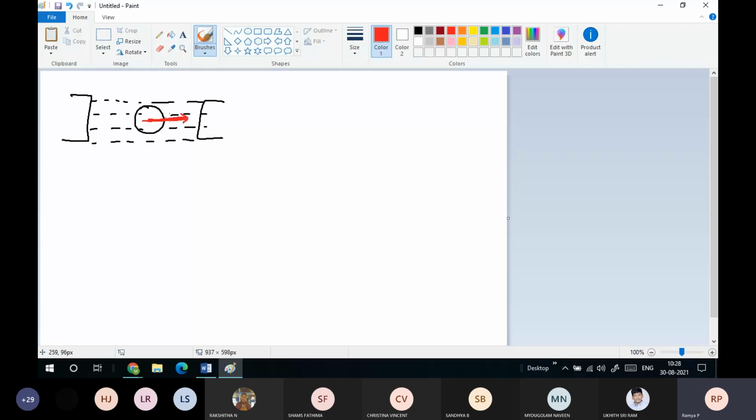Now see, the flux lines and the conductor shaft are both in phase, hence theta is equal to 0. So my EMF will be 0. Not to worry about this condition now. I'll go for the next condition. Now I will rotate this in an anti-clockwise direction. When I start rotating this conductor anti-clockwise, this indication marked with red, which was under the axis, will now come exactly opposite here.